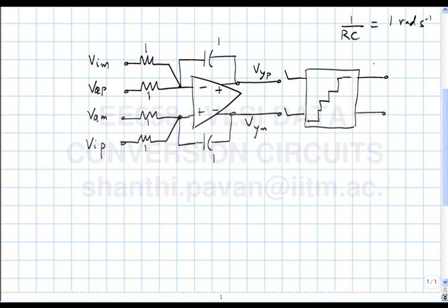This is the VQP, VQ. All right. So let's say you have a working op-amp and you have a working quantizer. Can you guess the most common mistake you're likely to make when you hook things up together? The sense of the feedback will be positive. Okay. So how do you make sure that the feedback is negative?